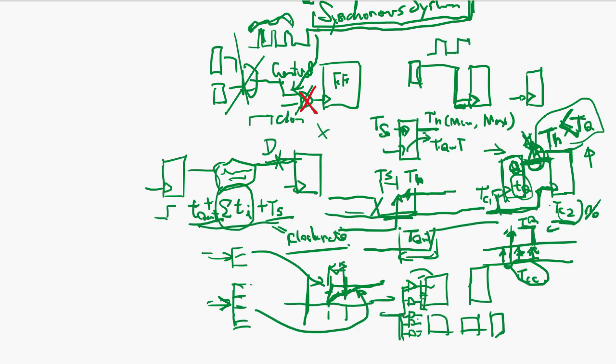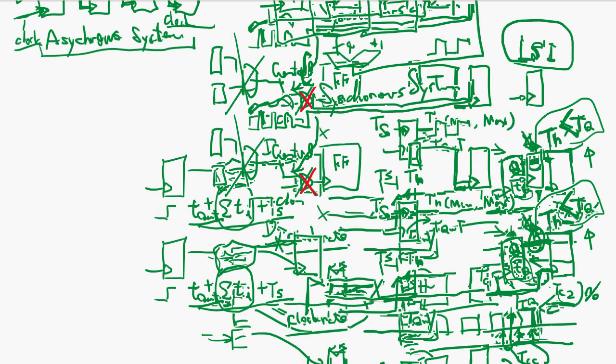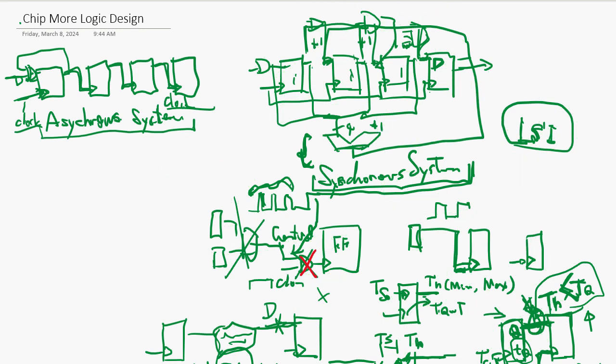So the clock has to be evenly distributed to the entire chip. Okay, so that's sensitive. When you're talking about very high speed, clock distribution becomes a really critical issue. So that's common in a synchronous system. This kind of thing you cannot handle in the HDL. So the logic designer has to pay attention to this.